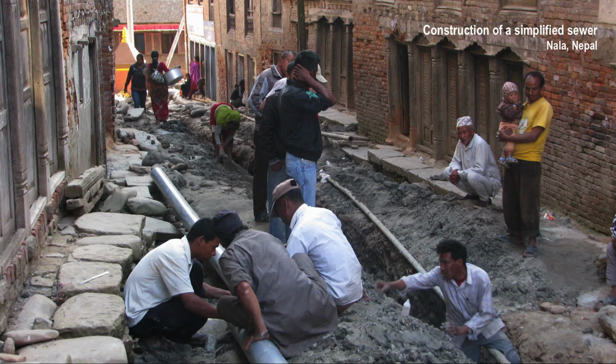Simplified sewers are especially appropriate for dense urban areas where space for on-site technologies is limited, such as in this picture. The drawback of the lower gradient and diameter of the pipes is that repairs and removal of blockages are more frequent. However, this can be done easily by locals at little cost. Such a system can be operated by the community itself. It is important that the users avoid disposing trash or other solids into the system. In all cases, occasional flushing is recommended to ensure against blockages.